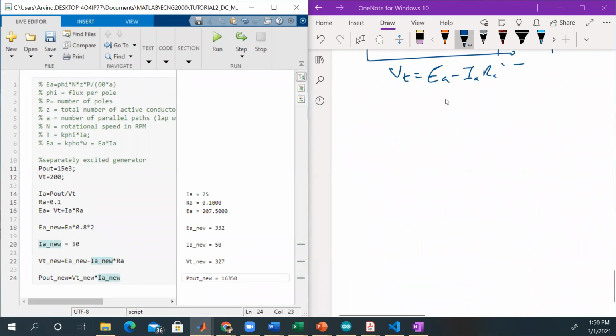Of course, you could always operate your motor beyond its ratings, but you can't do so indefinitely, and it will degrade the life of the motor. Same thing for a transformer, for any machine. The reason we have the ratings is these things are tied to the mechanical systems. And by the mechanical systems, I mean things like what is the clamping pressure on the windings, how much insulation it has, what is the thermal performance of the insulation.